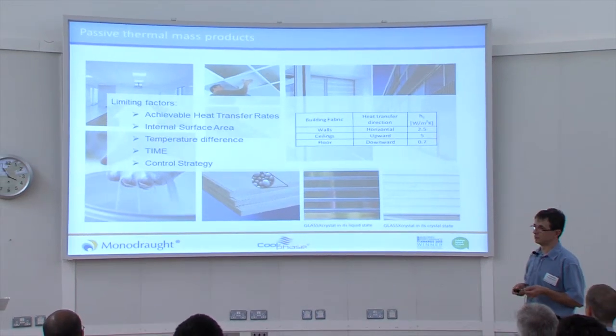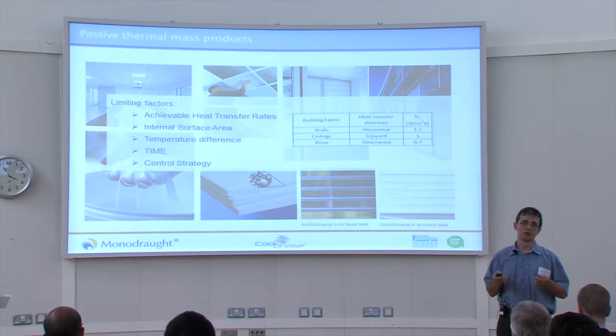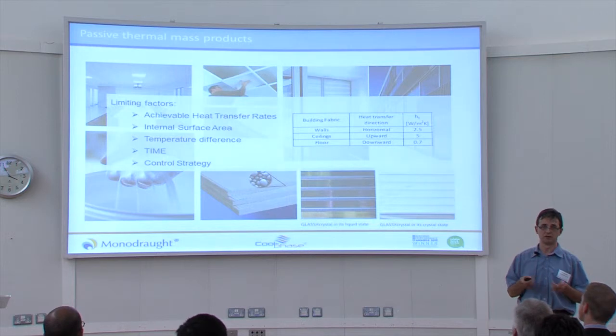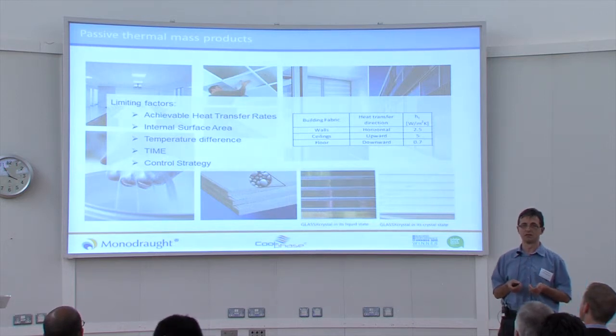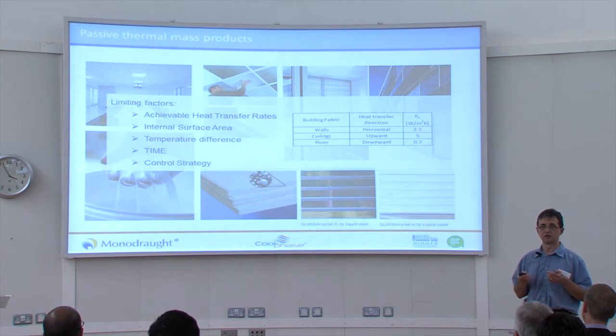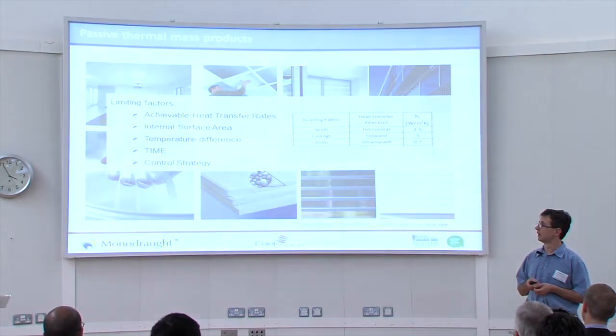However, we need to remember that with natural convection, especially when we are just using indoor materials, the natural convection is a bit limiting to the heat transfer from the air into the materials, and the other way back. So there are a couple of factors which are influencing this heat transfer. The heat transfer coefficient is fairly low. Then we have limited area available in a space, especially if we have furniture and other things.